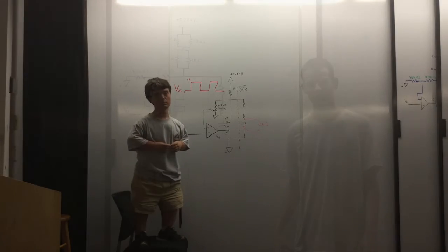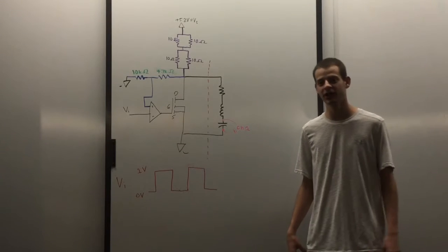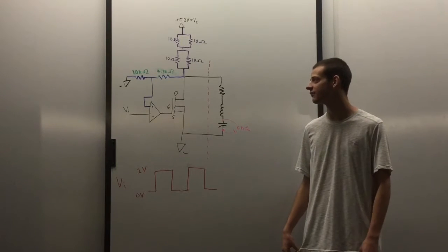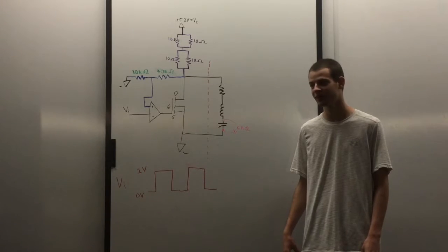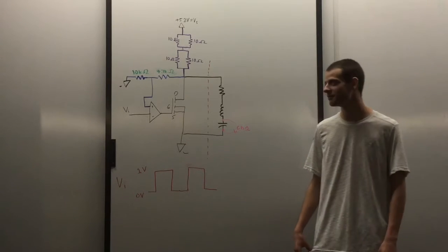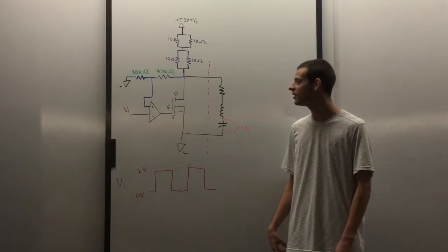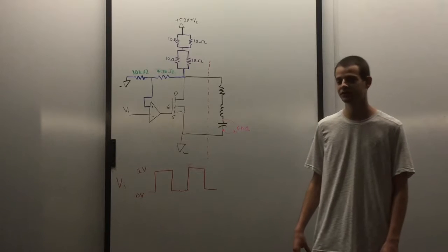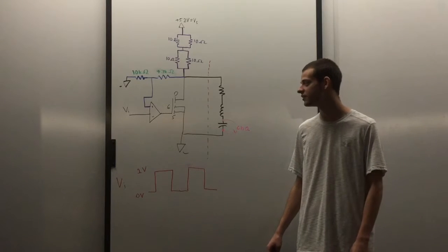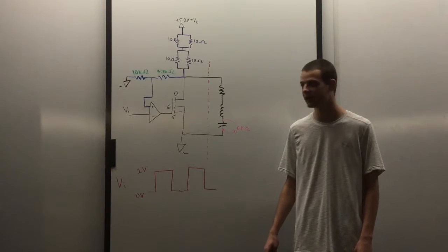Okay, during our original circuit, we had a couple issues which we then fixed in our revised version of the circuit. The first issue is with the 10 kilo ohm 10 turn trim pot, where we kept having issues with it moving around. So we then replaced it with a 10 kilo ohm resistor and a 4.7 kilo ohm resistor, which we created as a voltage divider, which fed into the non-inverting input of the amplifier.